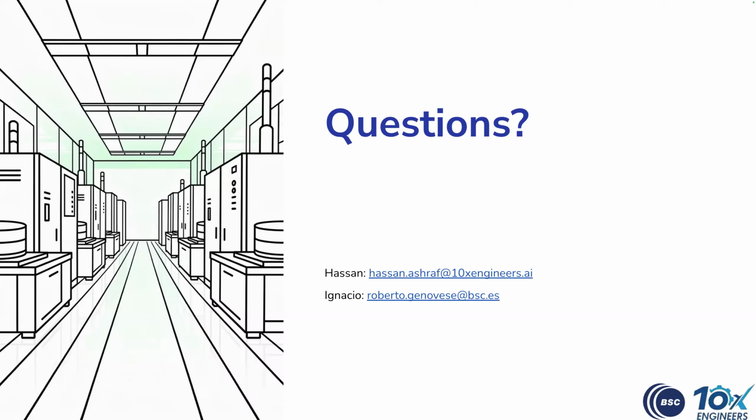Question number two, you talked about improving the coverage with three different aspects. One is simulation-based verification, second is using formal, and third is using the FPGA. In your graphs or circles, you mentioned that formal is the best to get the maximum coverage, and simulation is on the lower side. So maybe you can add some more comments on why formal is eventually the best, and why the UVM-based is the lowest.